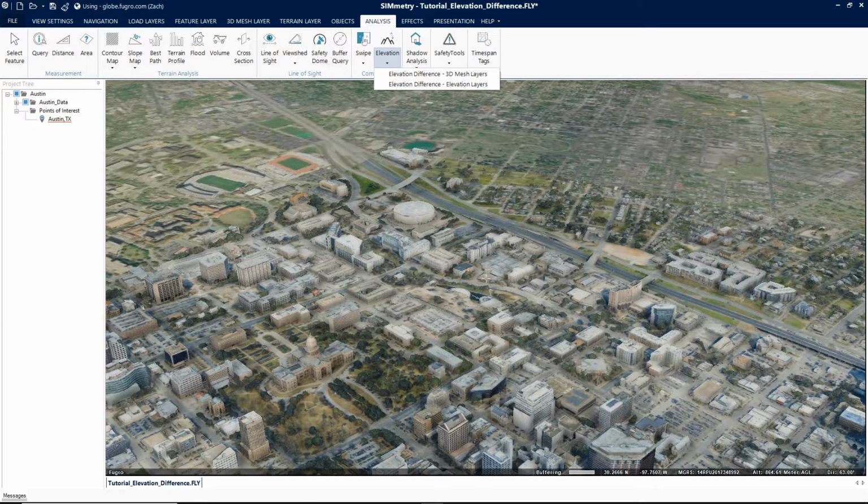Then, select either of the following methods to mark the area of interest: Draw Area or From Clipboard. The Draw Area method is marked by drawing a polygon in the 3D window. In the 3D window, left-click to define the points, then right-click to finish the drawing. The From Clipboard method analyzes the locations of all the polygon's clipboard objects.